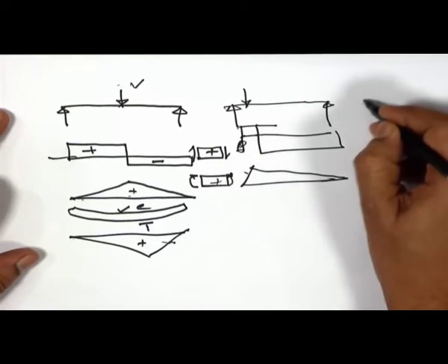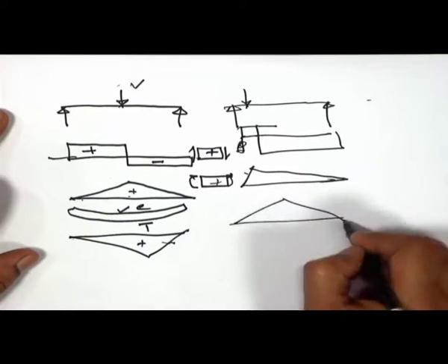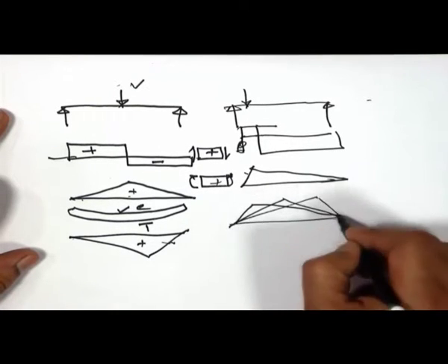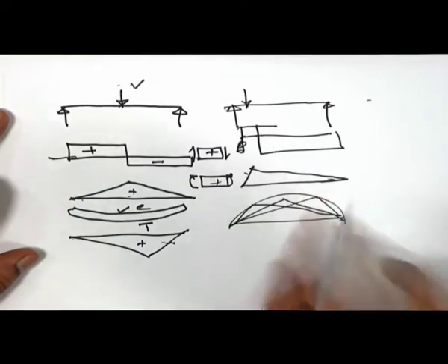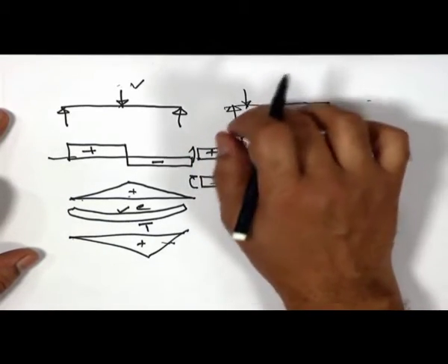Here, the things will actually change, and we will have a different bending moment diagram. Similarly, for different locations, we will draw different bending moment diagrams, plot them together, and then try to find out the profile, how it is changing. All these things need to happen before I understand the effect of the live load.